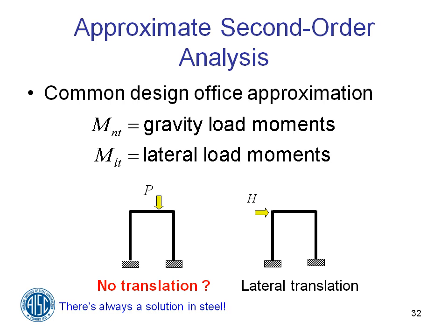However, in this situation that I've shown, the load is not in the center. And therefore, for gravity load, there will be some sway. And it's up to the designer to determine whether that is sufficient to be of concern, in which case you would have to go through an analysis that takes out the side sway for the gravity load.